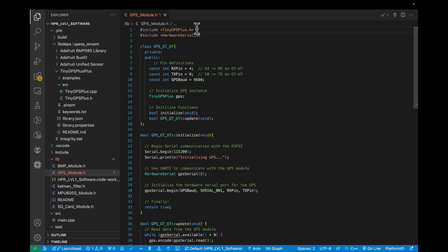But those libraries were really heavy to run, which is kind of strange. What could there be to run in a GPS, right? That's the thought that comes to mind. But yeah, they were quite demanding on small embedded systems like ESPs and STMs. So there's another version called Tiny GPS, a tiny version of that. These are pretty lightweight libraries, and most of the functionalities are still in them, even though they are not as demanding. So that's the reason why I'm using that one.